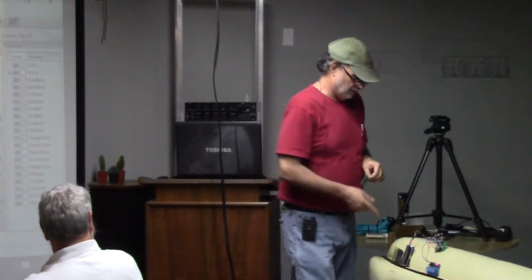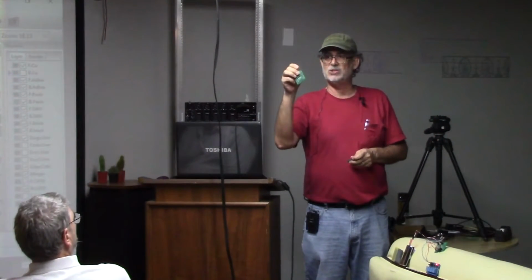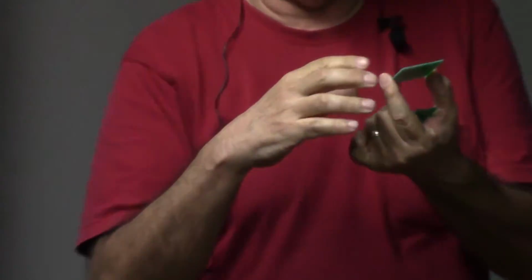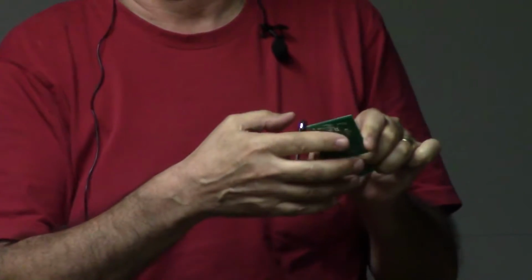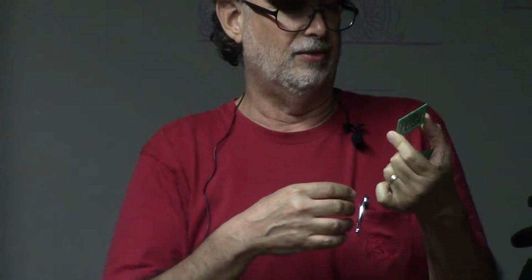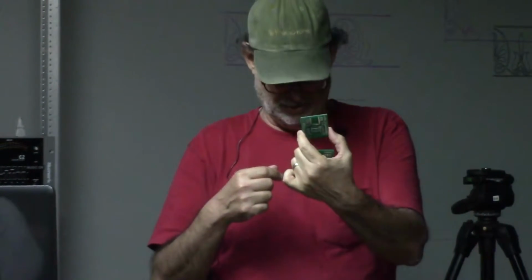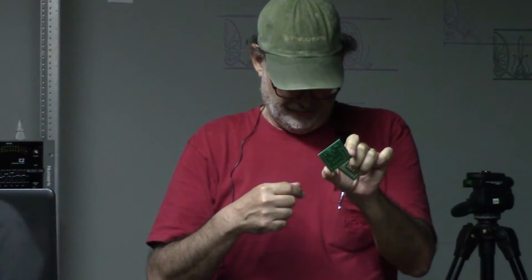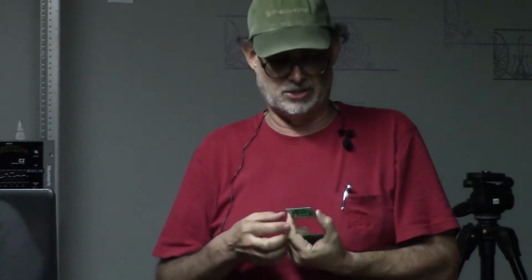So I expanded on my original design. I made this more of a development system board. There's a voltage regulator mounted on the back that can take an input up to 50 volts to give me 3.3 volts to run everything else on the board. I have an analog input, so I can measure an outside voltage up to 50 volts and use that outside voltage that I'm measuring to run the device. I've got obviously digital outputs because we're controlling relays here. I have digital inputs.